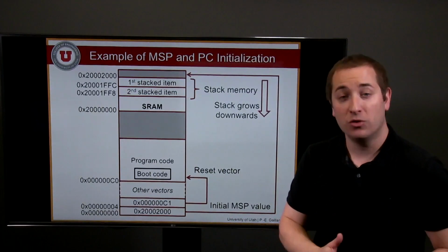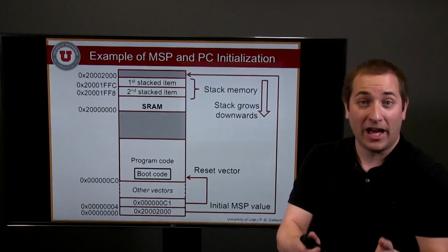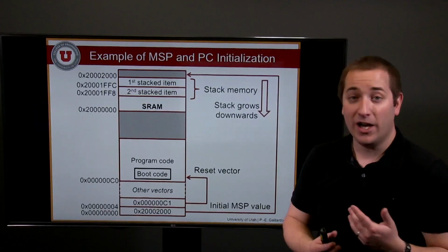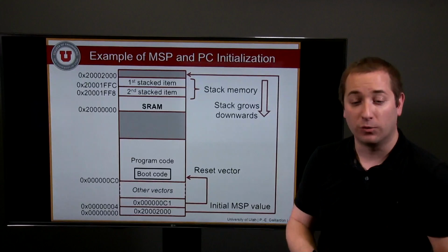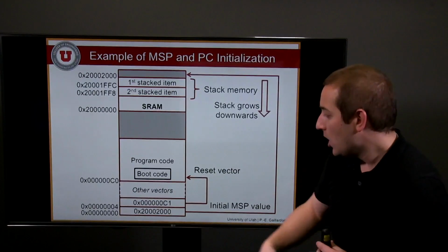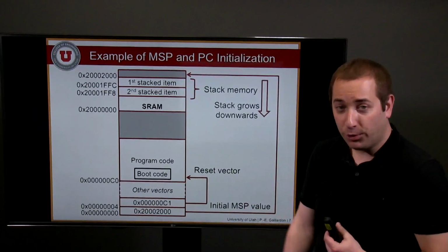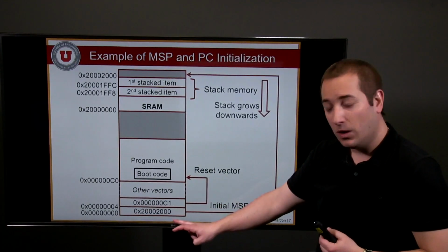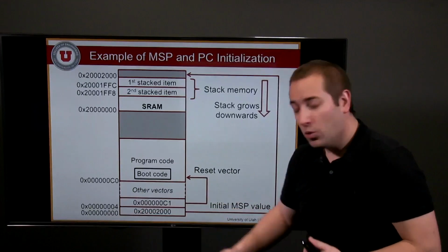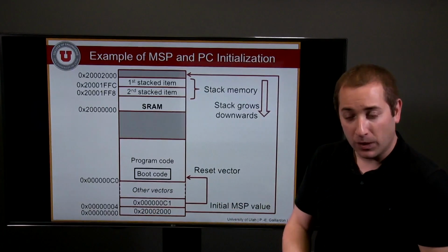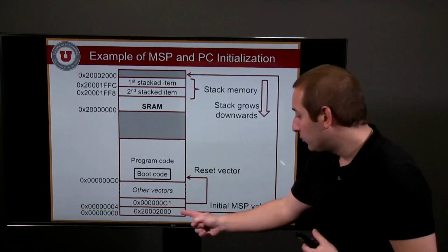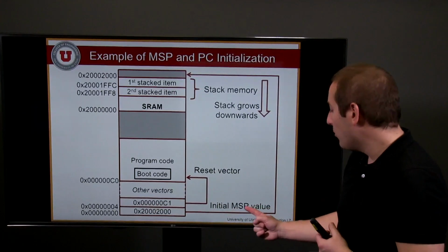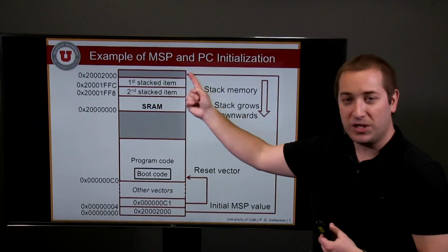Those are the locations where we have a physical memory attached to it. The memory being either an SRAM, a flash, and so on and so forth, different memory technologies. What does that mean? At processor startup, we'll look at the content of address 0. At address 0, when we programmed our microcontroller, we smartly put the address of our memory stack pointer, the initial value of the memory stack pointer.